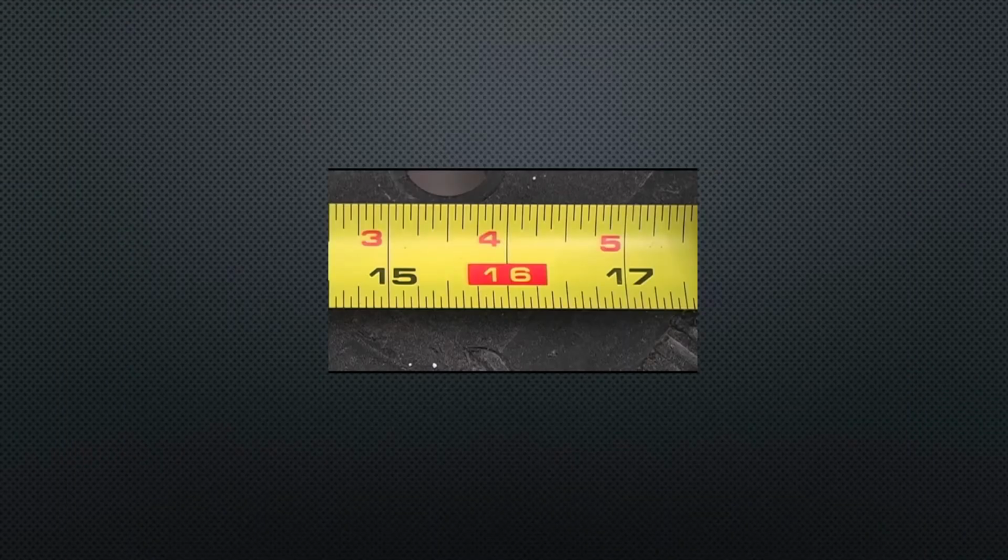And one final thing, just before we move into the SketchUp part of the day and the demonstration part, a little bit of trivia. Tape measures usually will have the stud locations marked on them. So if you look at this tape measure, the 16 is in red, and you'll see that on a lot of tapes. If the 16 is in red, then the 32 will be in red, and the 48 will be in red, and so on. Those are where the centers of the studs can go.